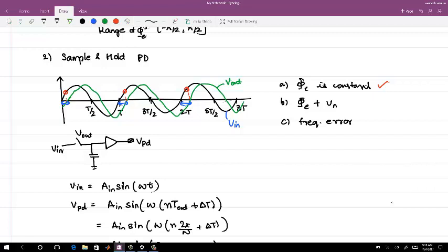And in case of regular PLLs, what happens is that your output frequency is some multiple of the input frequency. So when you are sampling the output frequency, you sample once in a while. Just as an example, let's say F out is 8 gigahertz, and F ref, the reference frequency, is 1 gigahertz. So this is a heavily aliased spectrum if I used fref for sampling the output.